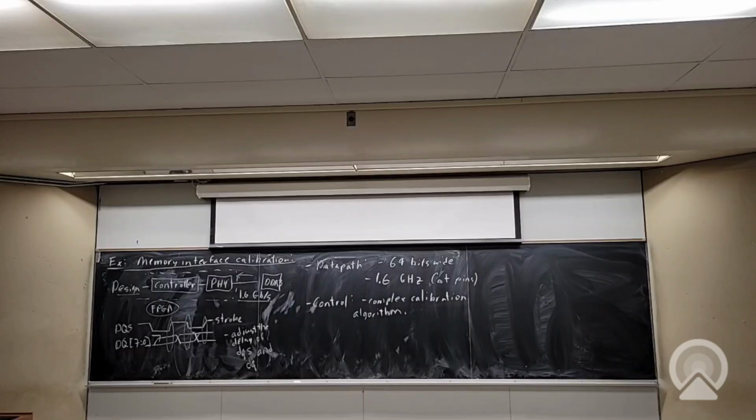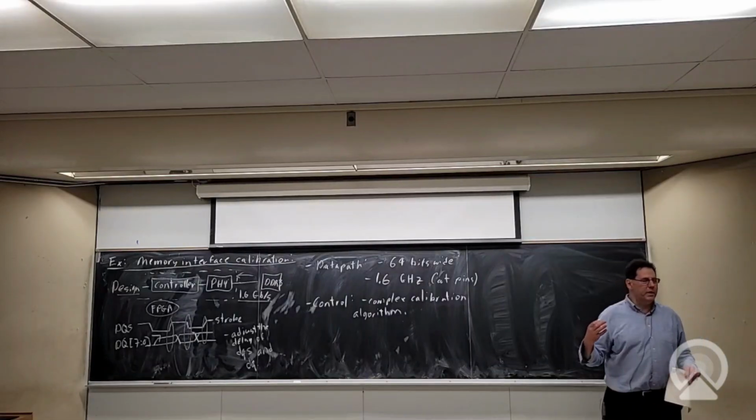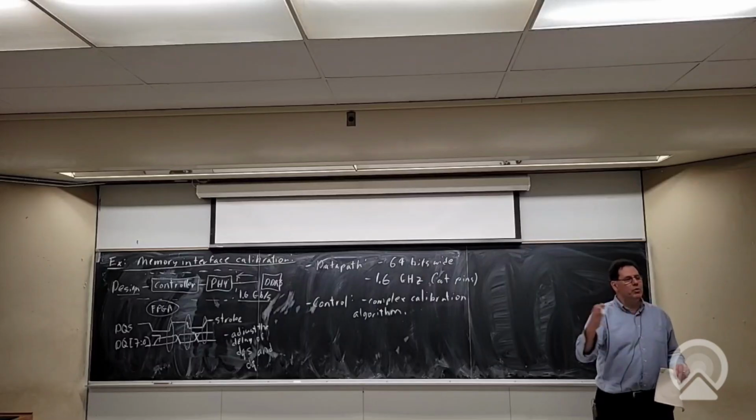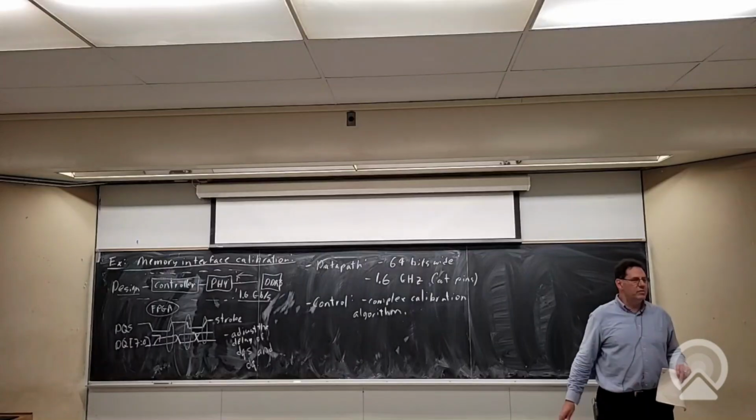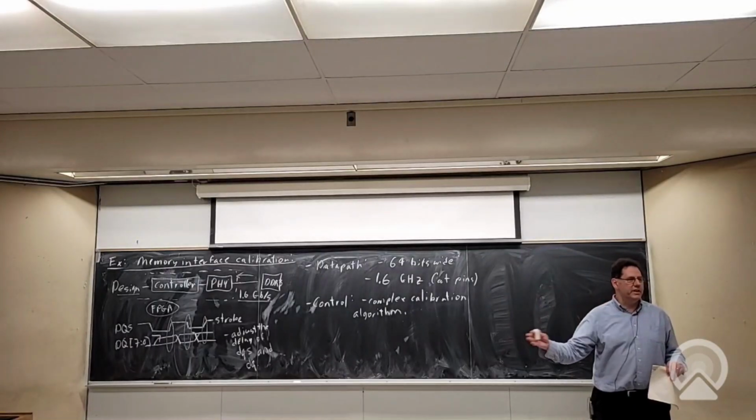Internally, the DRAM's a bit more complicated than this, but you can think of it as being a 2D array of capacitors connected to bit lines. You send an activate command, and a row of data is sensed. Sense amps are differential amplifiers that sense a little bit of a negative charge or a little bit of a positive charge in that capacitor, and they store it in latches. You get a whole bunch of data in latches, maybe 8 kilobits when you do an activate. Then you can read it out with read commands, which actually read from those latches. And the CL is basically the latency from the read command to the data coming out.